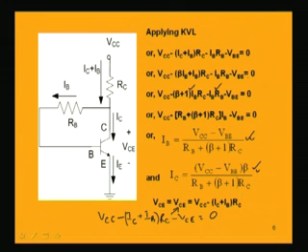Likewise as we have seen earlier in the emitter bias configuration, if we can make the value of RB very small in comparison with the other term in the denominator, that is (beta plus 1) RC, then we can write this whole expression as having in the denominator (beta plus 1) RC.